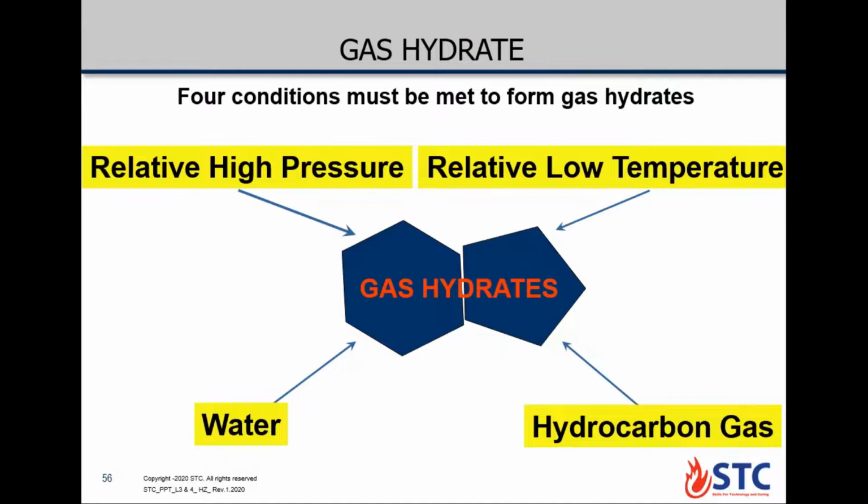Okay, gas hydrates usually are a conversion of the gas, under some conditions, to ice mush, ice plugs. It plugs the circulation path. The problem with gas hydrate is that it creates complications during the killing operation by stopping the circulation path. So this is the problem, it gives trapped pressure upstream of the gas hydrate. The gas hydrate can only form under 4 conditions together.